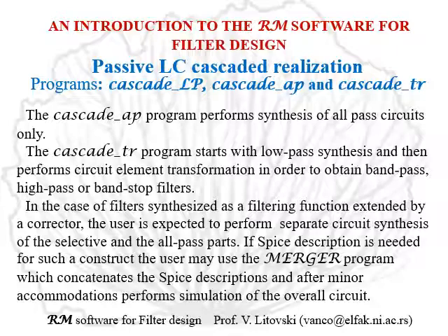If a SPICE description is needed for such a construct, the user may use the merger program, which concatenates the SPICE descriptions of the filter and corrector, and after minor accommodations, performs simulation of the overall circuit.